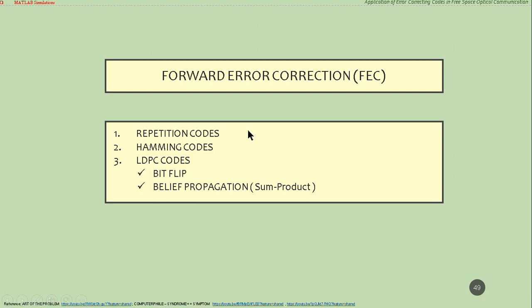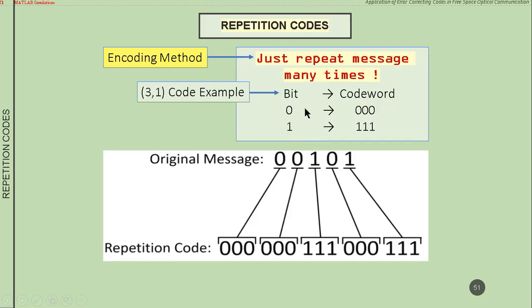Now implement the FEC scheme. Let's start with the simple repetition code. In a repetition code, we have just one bit. It is repeated more times so that we ensure that it is received as sent. Errors will strike and change 1 bit or 2 bits. If we are lucky, and only one bit is changed, then with the majority rule we will be able to tell that it was a 0 that was sent.